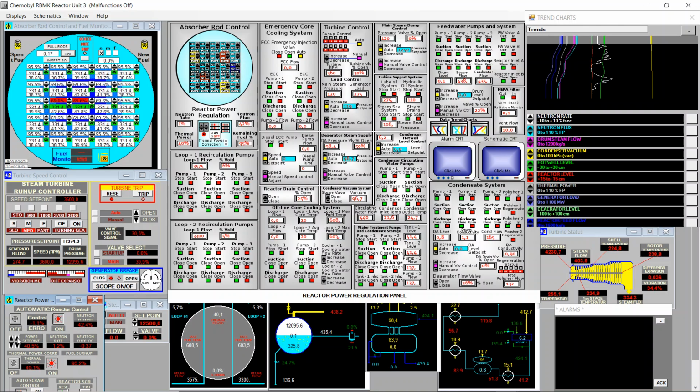Okay. Also with the turbine, you saw we had no problem at all with vibration or differential expansion. That's also nice. So I didn't need to talk a lot about rotor temperatures and shell temperatures, but I was looking at them during the spin up, and the difference between the two was a maximum of 20 or 30 degrees. And the differential expansion, which is plotted here, was always between these two red areas. The left one means the rotor is cooler than the shell, and the right one means the rotor is warmer than the shell.